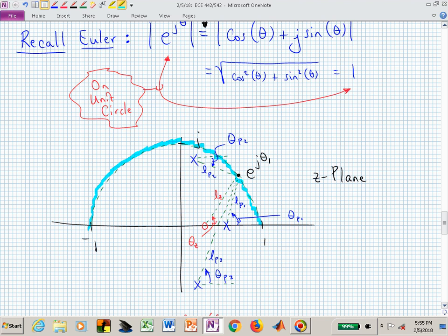How many think it's first order, second order, third order, fourth order, fifth order? I had more threes, third order. Why is it third order? I see 4 points up here. I see 3 X's and an O. Why did you vote for 3? It only depends on the poles, doesn't it, the system order. So it's third order based on the 3 X's.